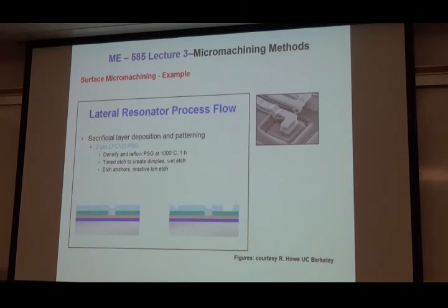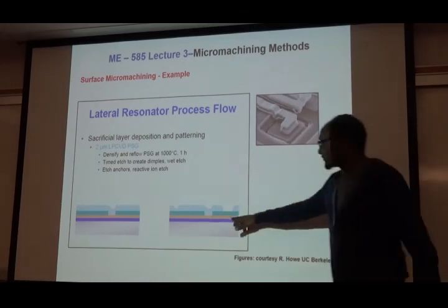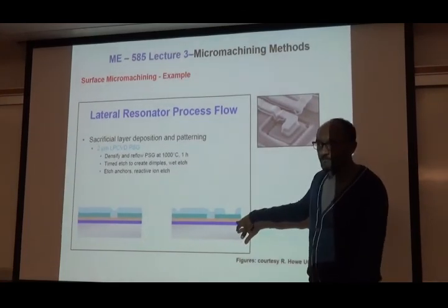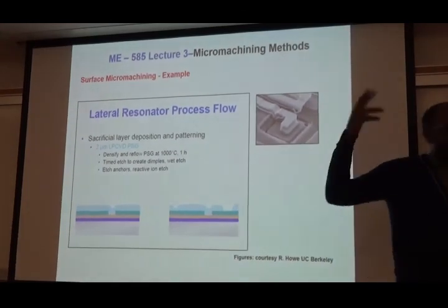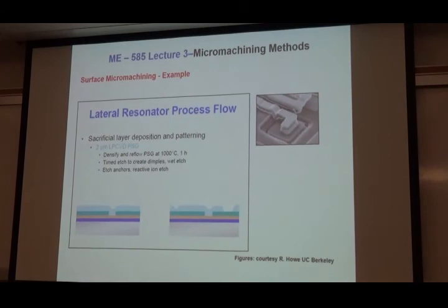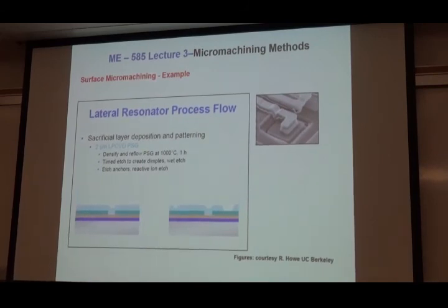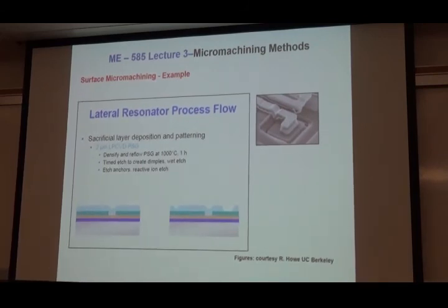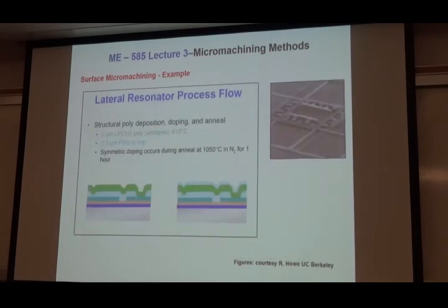So remember, this is just a sacrificial layer. So after the sacrificial layer comes some structural layer, right? I have to have something that's going to float. If you've already done your homework, then you already know what's going to come. So this guy, I call it poly 0, the orange one. Now another poly layer is coming, and I'm going to call that poly 1. Okay? And you're going to see that. All right, the green one.